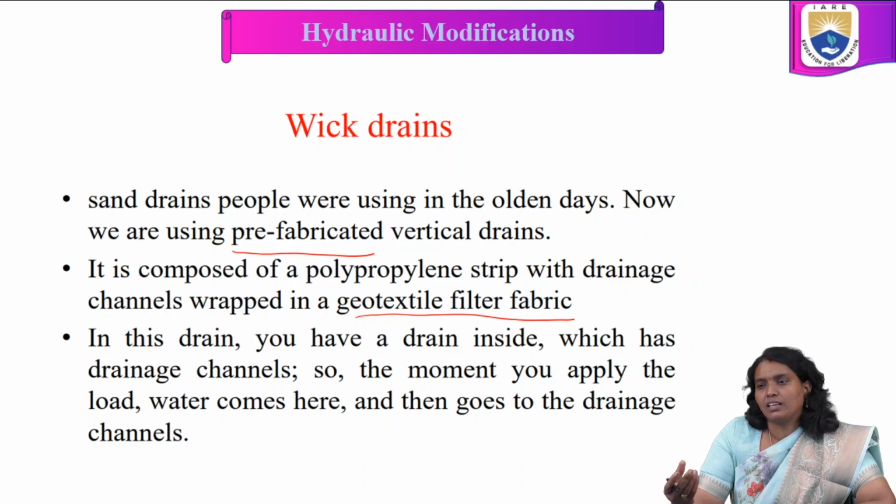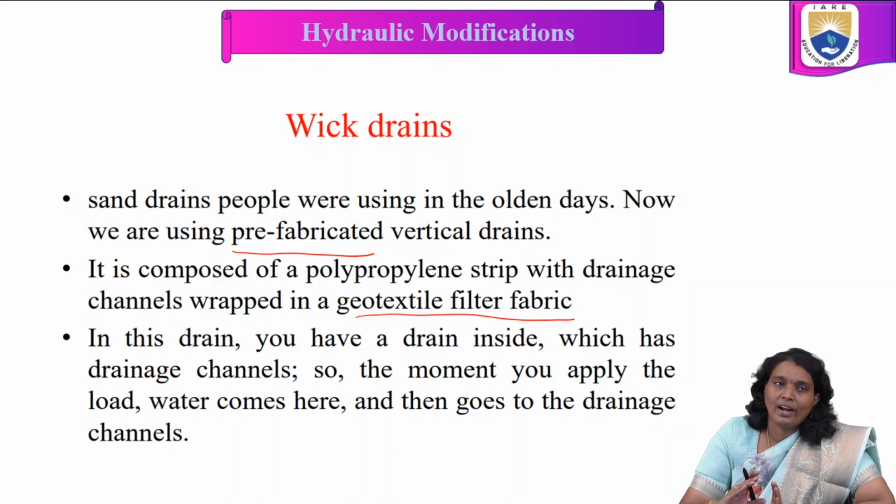Once we observe absorption of water by the soil and some leakages, they may affect the required properties and desired parameters. But with wick drains, being prefabricated, we may overcome these disadvantages of sand drains.